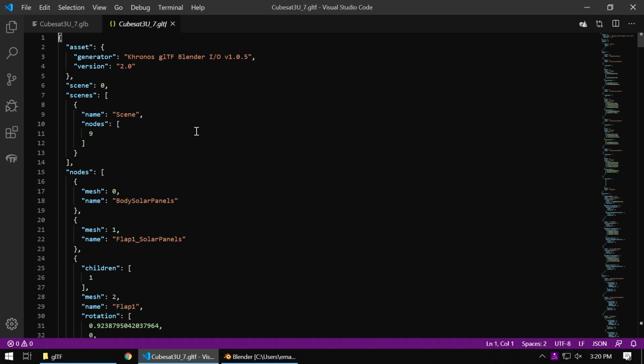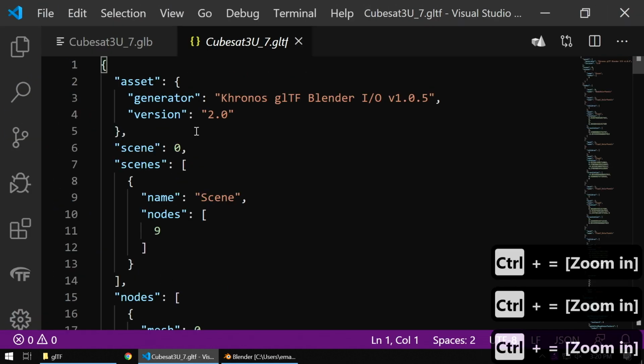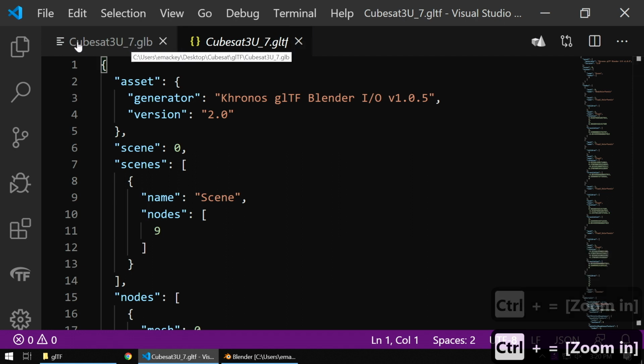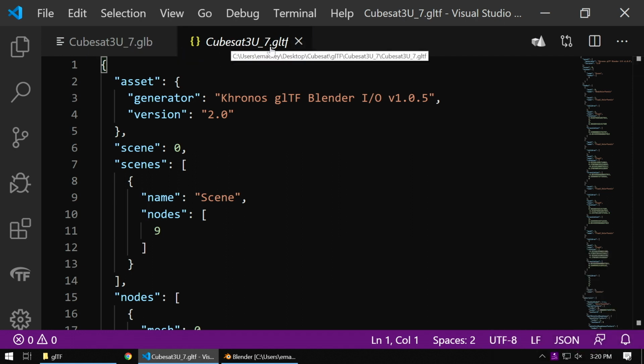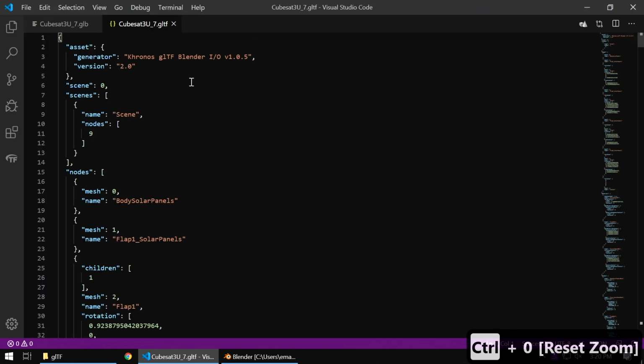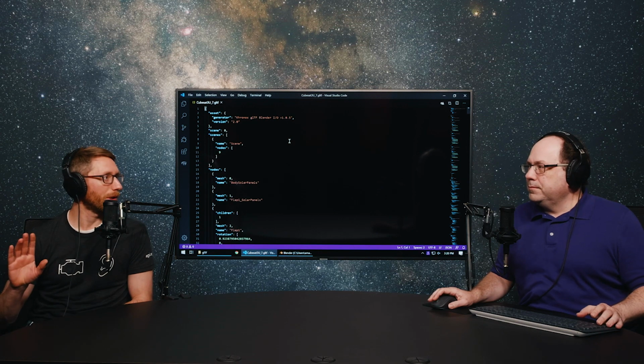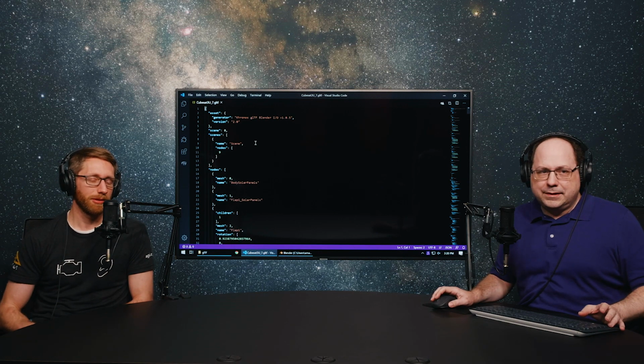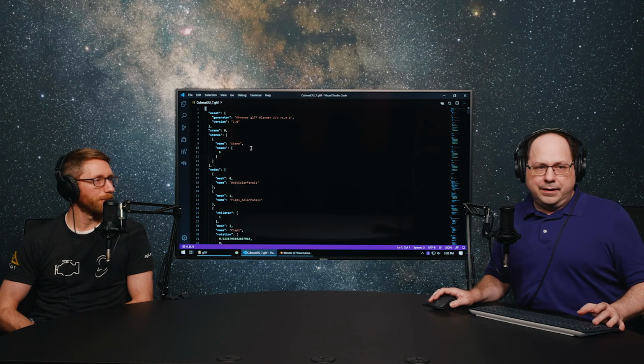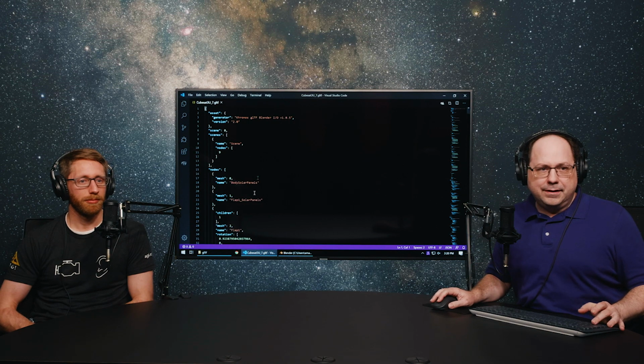And one more little point I'm going to make, if we take a quick look up here, this is ordinary text and this is italics. Italics is a warning. It means that's a temporary window. If you double click on it, it stops being italics, and then it's not a temporary window anymore. By temporary, meaning that if you did a search and pulled up another temporary window, it would just replace the contents of that. So I would recommend you make sure that that's like that.